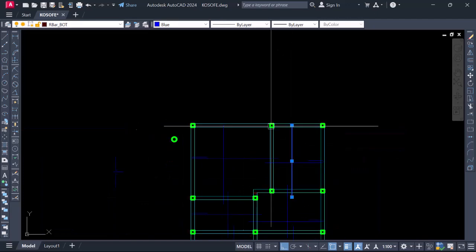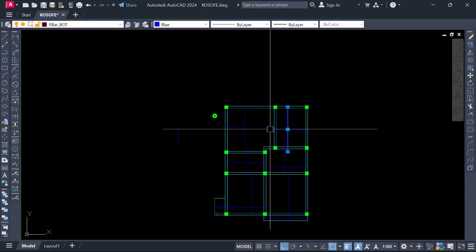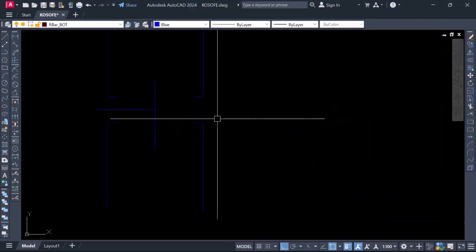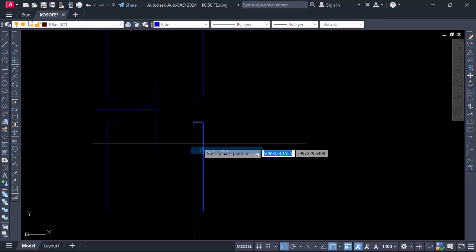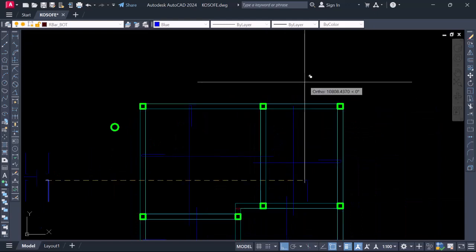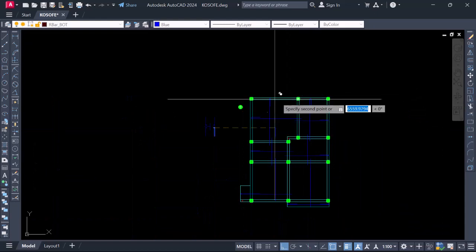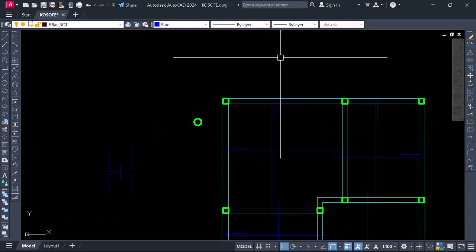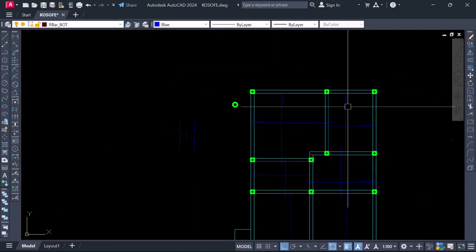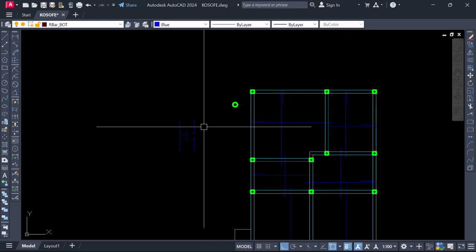So this is not going to start from here. You're going to start inside the beam, right inside the beam, like what we have over here. So in doing this, we're going to create a return for all these bars. In mirroring that, we just have to mirror our reinforcement. We pick our reinforcement, copy it out, pick it here, and click over here. So what we are going to do here is just click all over where we have our termination, because we don't have slab in this area. The slab is starting from this beam and running towards this beam, as we said earlier, panel by panel. So we don't have anything along this area. So this is the terminating point, all right? The same thing we're going to do over here.